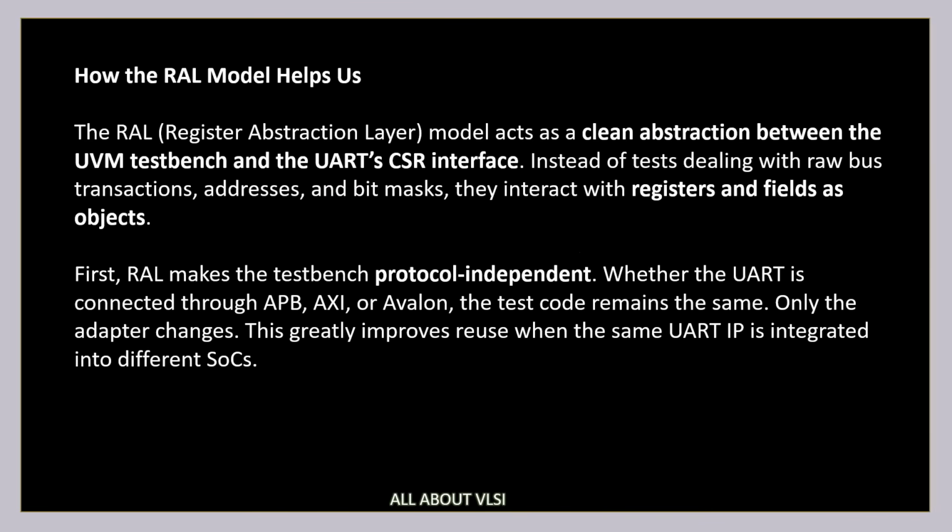Basically, this RAL model is a clean abstraction between the UVM test bench and the UART CSR interface. Instead of tests dealing with raw bus transaction addresses and bit masking, they interact with the registers and fields as objects. So RAL makes the test bench protocol independent, whether the UART is connected through APB or any other interface. The test code remains the same. Only the adapter changes. We will have something known as an adapter that we are going to discuss in later sessions.